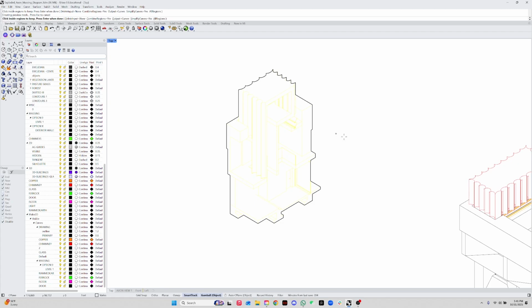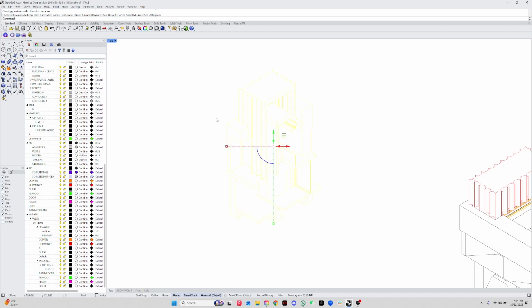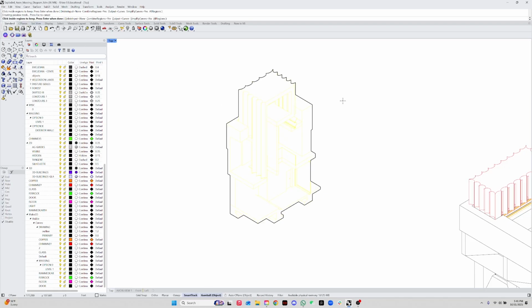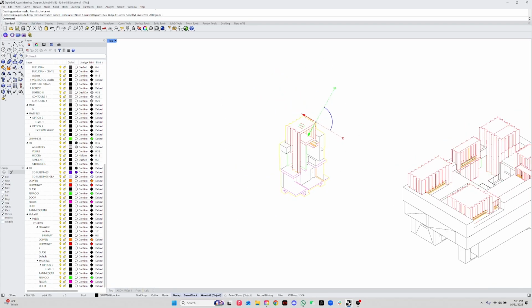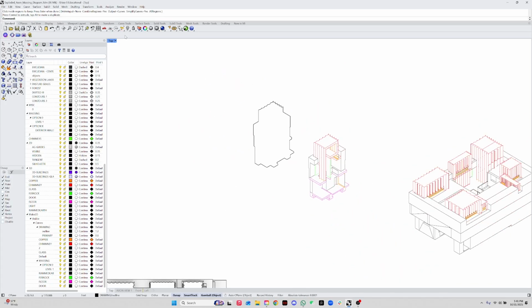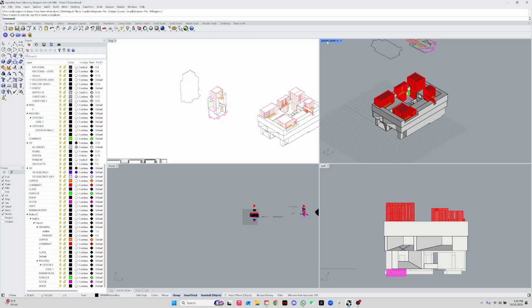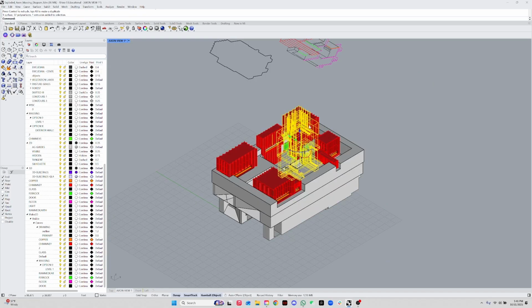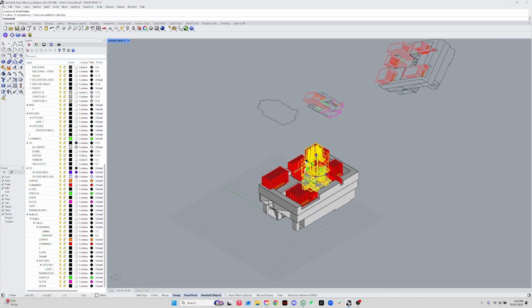But if you don't do a mesh outline from the model, you can also do a curve boolean like I'm doing. So again, you select your model, you do curve boolean, then you select the outside of the model so it grabs the outline, and then there you go, you have your outline of your model now. So that's why outline. If you want to do it the other way, you can go back to your view, go to the model, you do mesh outline.